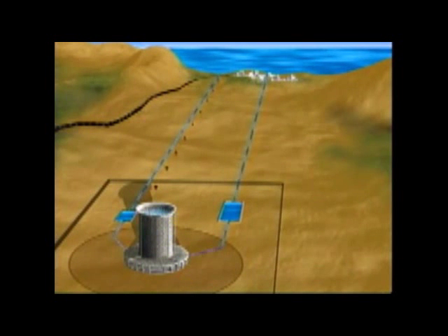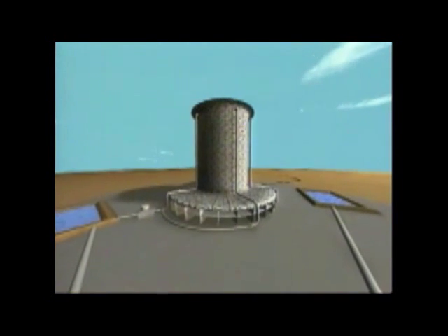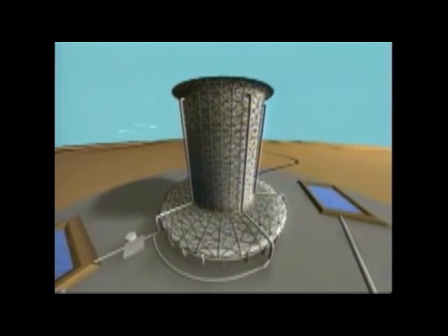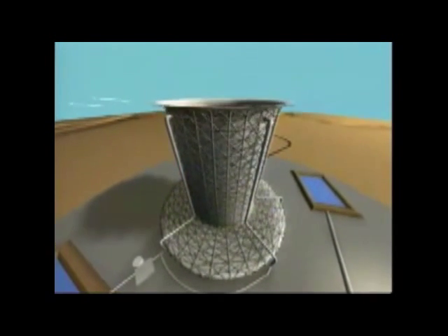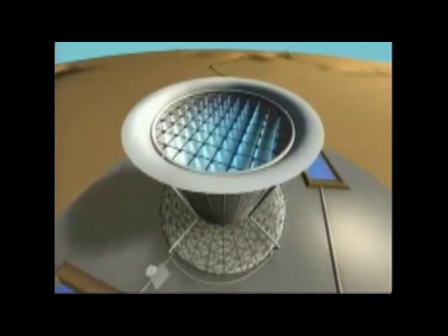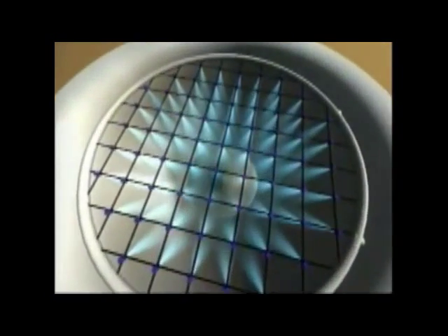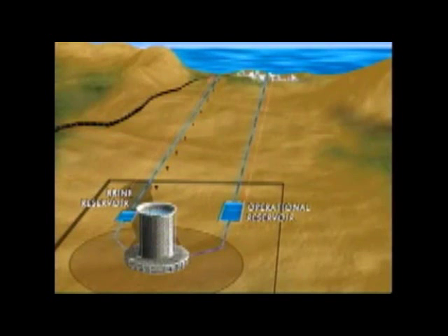The energy towers will be located in a hot, dry area near a large water source, such as an ocean or a sea. The seawater is delivered by pipes or canal to the operational reservoir, and then pumped to the top of the tower. There, the water is sprayed in small droplets by a spraying system into the hot, dry air, evaporating and cooling the air. As the air cools, it falls and gains high velocity. The wind speed can reach 50 miles or 80 kilometers per hour, rotating turbines located at the bottom of the tower and producing electricity. The brine residue is collected and stored in the brine reservoir, and from there it is conveyed by pipe back to the sea.